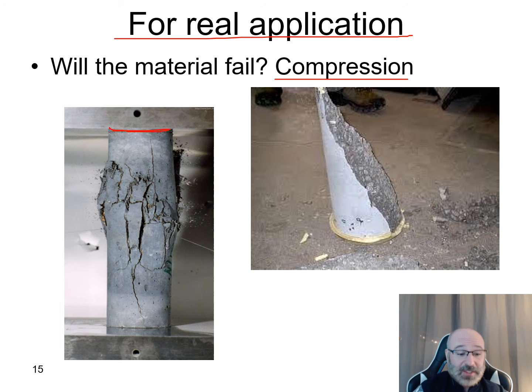We're looking at bridge decks and we're seeing a lot of delaminations, a lot of spalling, a lot of potentially potholes coming up to the surface. So we want to see, is this something with the concrete itself? And one of the questions, particularly in my research, is the porosity of the concrete. We can get some information on that from these core samples and doing some of these compression tests as well.